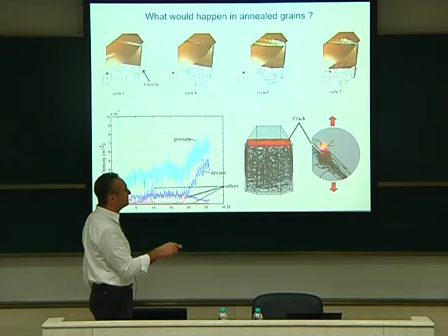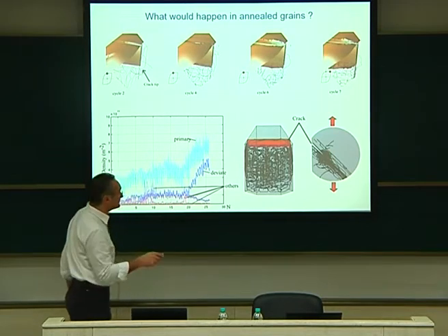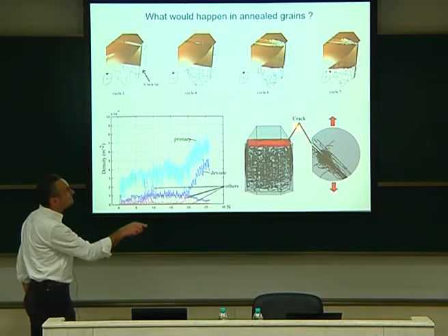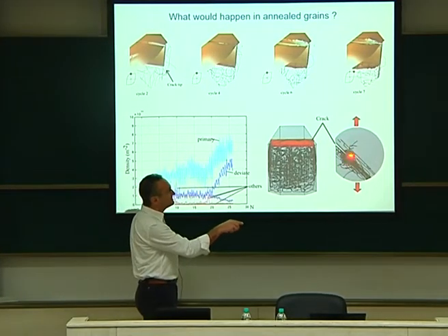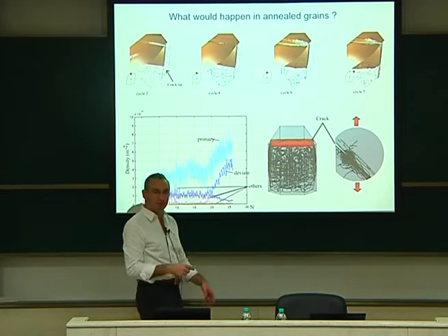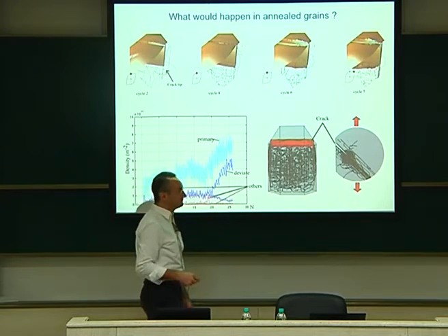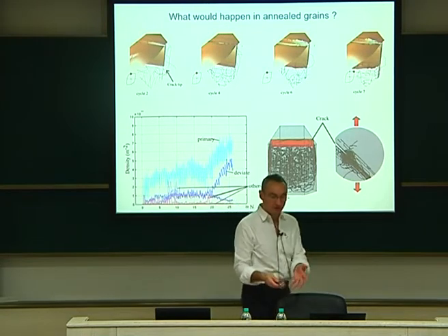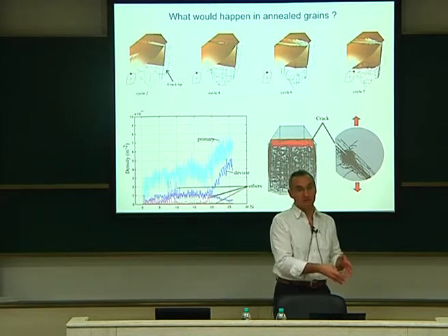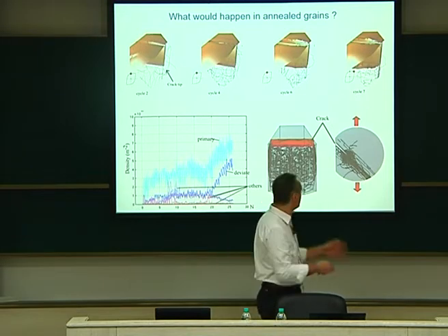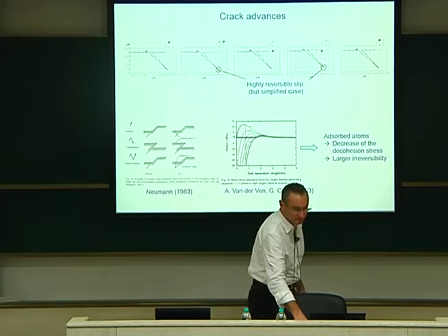It's indeed similar to what we did with MD. So here you can see that it is not easy for the crack to advance because there will be this hardening here, this forest microstructure that will be very complicated to interact with the crack. So this is something different. It means that a crack in fatigue would be very much different from a crack in a non-deformed grain. There's very much difference between the two.